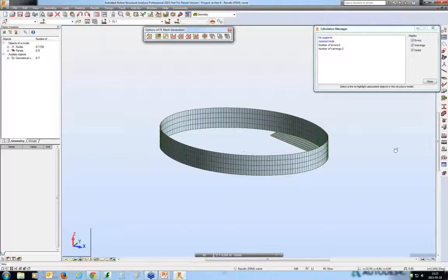The reason I deleted the meshes during the presentation is only to show in a clear way that you can see the mesh is deleted and generated again. Running that directly is like replacing the old mesh with the new one, and you may just skip the part where the mesh was first deleted. So you do not have to delete the mesh unless you have a frozen panel and you want to do this.